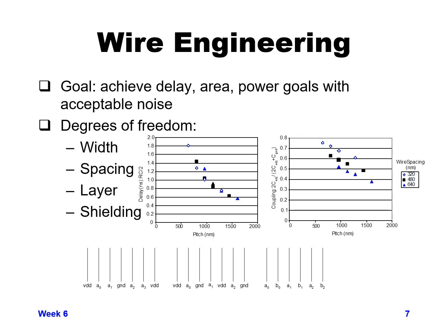But it doesn't necessarily help as far as noise goes, because both A0 and A1 can both switch in the same direction and be attackers on B0 at the same time. So logical shielding can sometimes help for one type of noise effect, like the Miller coupling effect and delay, causing extra delay effect, but it might hurt for other types of effects like noise effects, as I just talked about.